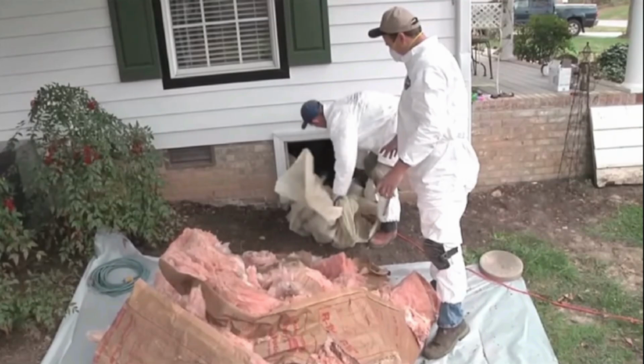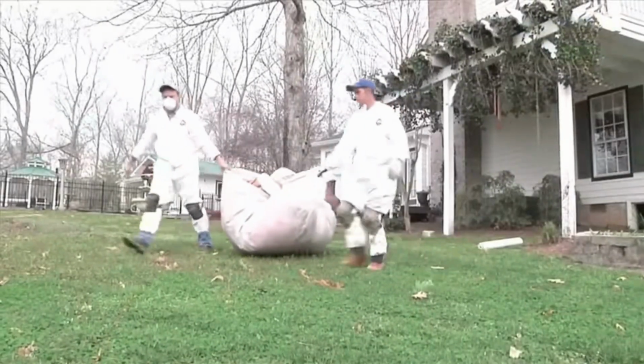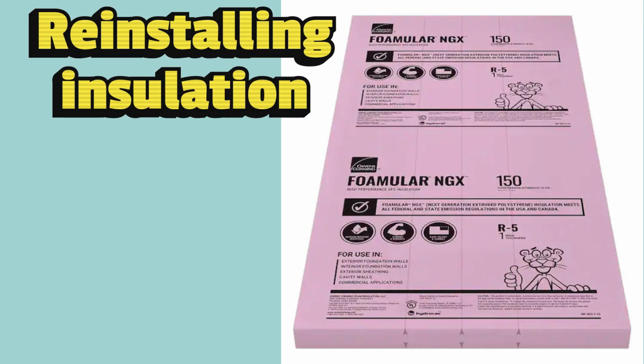As you're pulling the insulation from the bottom of the subfloor, use a tarp to stack the insulation on and pull it in batches. This is much easier than dragging it piece by piece out of the crawl space and to the haul-away point. Reinstalling insulation.